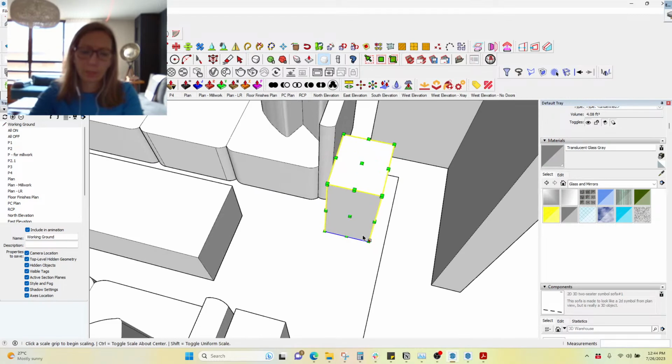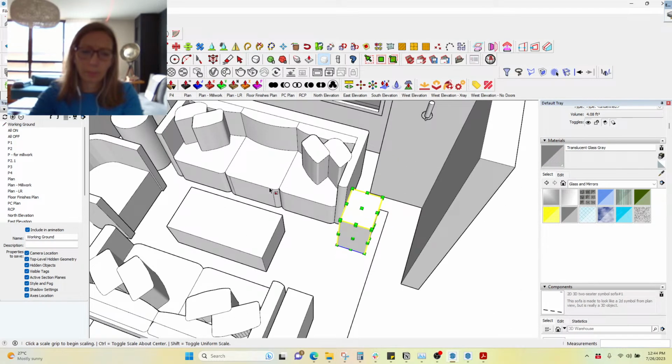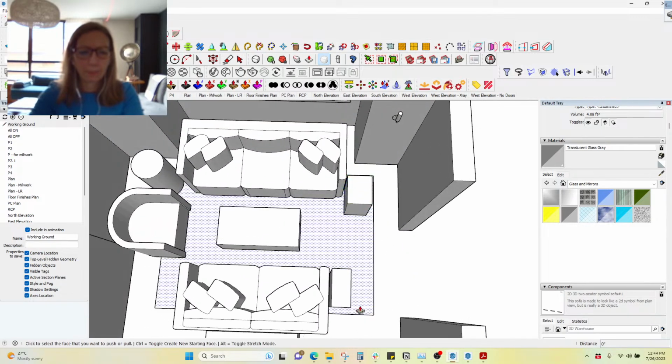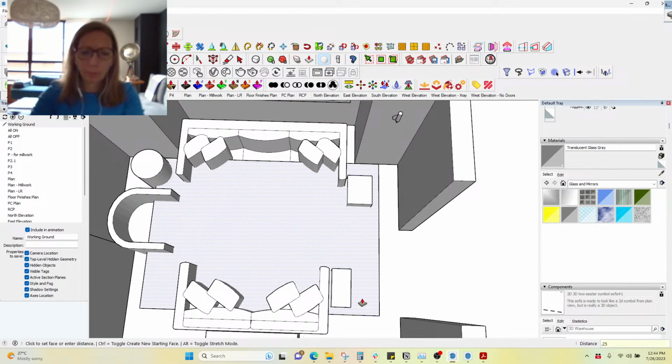So I just use these blocks. The reason why I make them 3D is that it looks better in 2D so you don't get the graphic issues, but it's also easier to space plan without them being heavy furniture models. And then I extrude this by 0.25.